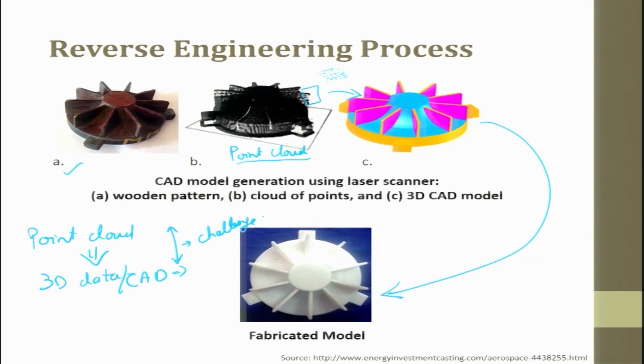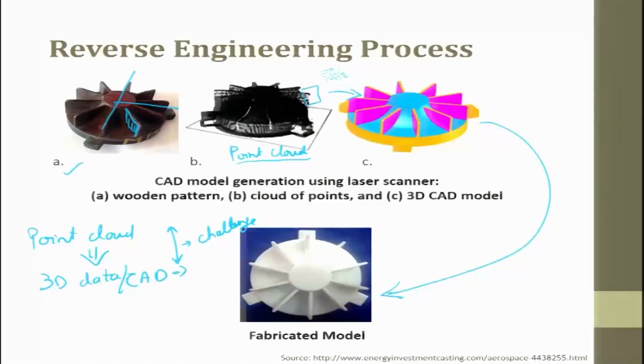See, here it is an engineered part. So, in an engineered part, you can always take only half of the data, or even a quarter of the data, and you can say, okay, spin it off, revolve, you will get the same thing. And here, if it is a straight line, okay, if you can measure the depth, I can sweep this and get the data. But in reality, when there is a 3D object where there is varying radius, for example, your face, varying radius, getting point cloud data is a challenge, and then working on the data, converting or smoothing out, is very difficult.